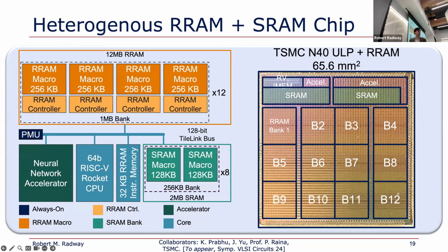Yeah. Would you only use the SRAM if you're doing the on-device? No, we use it for buffering, right? So when you get your first input, you need to store that entire token string somewhere. So that goes into the SRAM. Then you do your tensor operation for the first layer, and you have intermediate values every layer. So you write those back into SRAM.